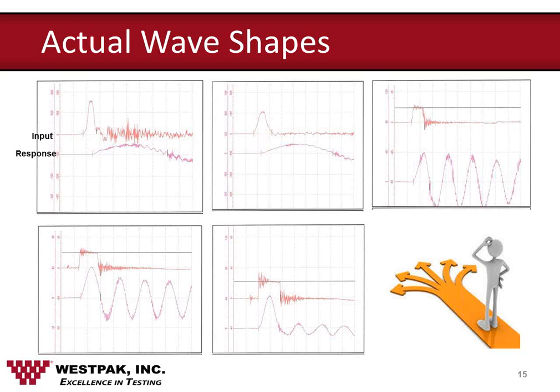The next pulse shows the beginning of a trapezoidal pulse with a response below it that is clearly of higher amplitude than the input. So here's our trapezoidal pulse with a mean or faired acceleration level here, but you can see that the response is now double the input, and so we have crossed our 1/2 threshold between the frequency of the response and the frequency of the input.